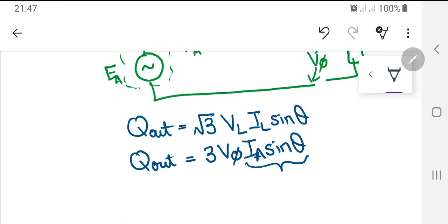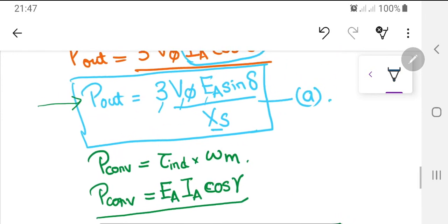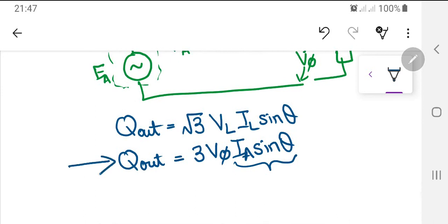Why? Maybe you can come up with some expression, but it's not needed. The answer is a little bit tricky. Generators, whenever they are run, are always run for their electrical power, that is, active power. Reactive power is never required from a generator, supposedly a generator at Tarbela Dam or Mangla Dam or anywhere else. We always require the active power. The reactive power is generated by capacitors near your grid stations, so that it doesn't need to go towards Tarbela Dam or Mangla Dam or your powerhouses.